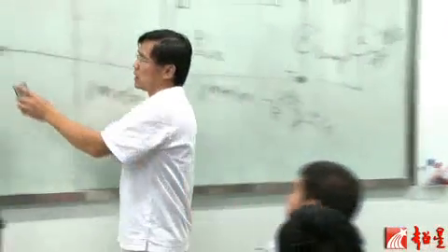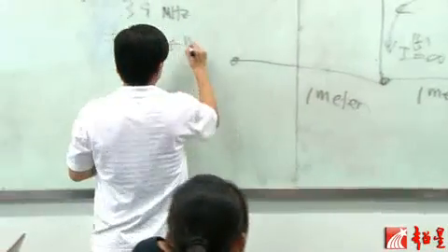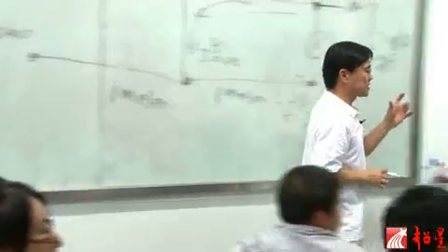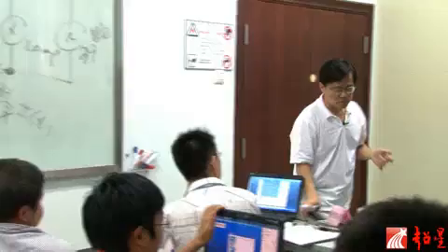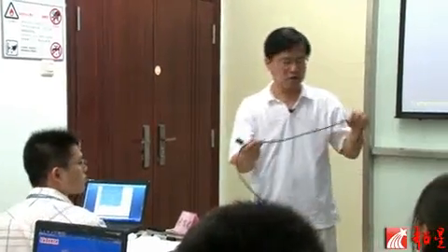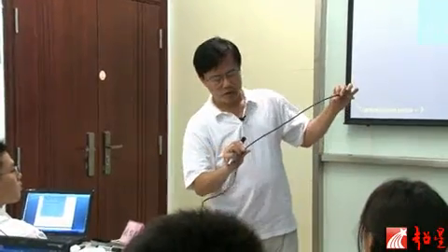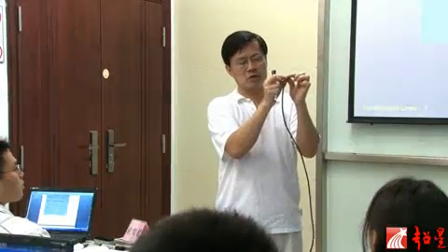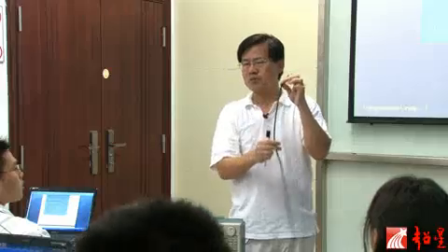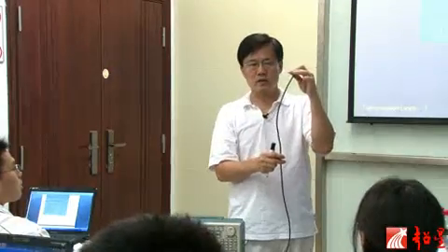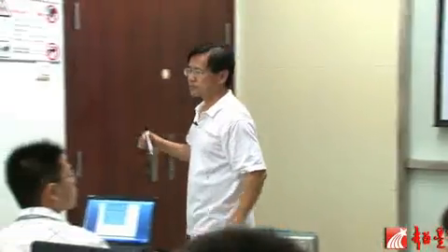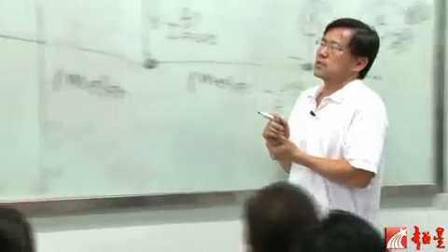But in a cable, most cables are so-called 60% cables. Some cables will tell you the speed of the cable. This one doesn't have any marker. So usually the speed the electromagnetic wave travels inside the cable is much slower than the speed of light. It's about 60% of the speed of light. So basically, let's say it's 60%.